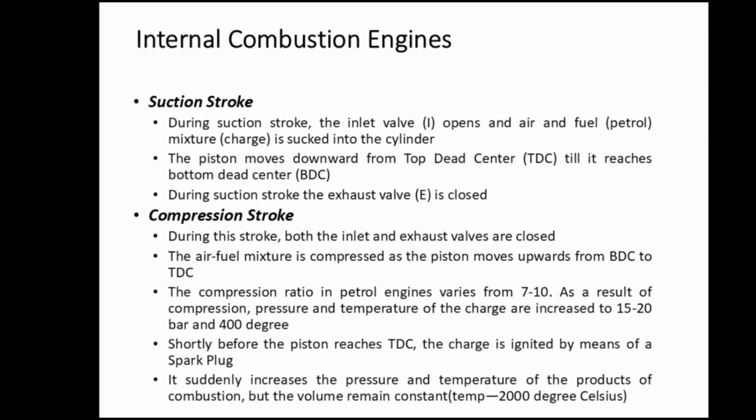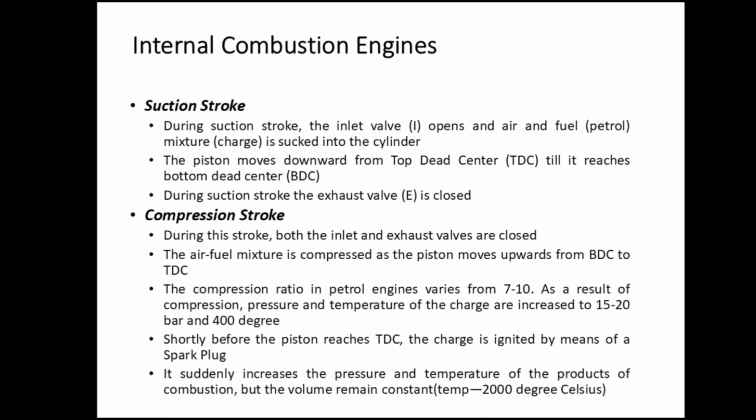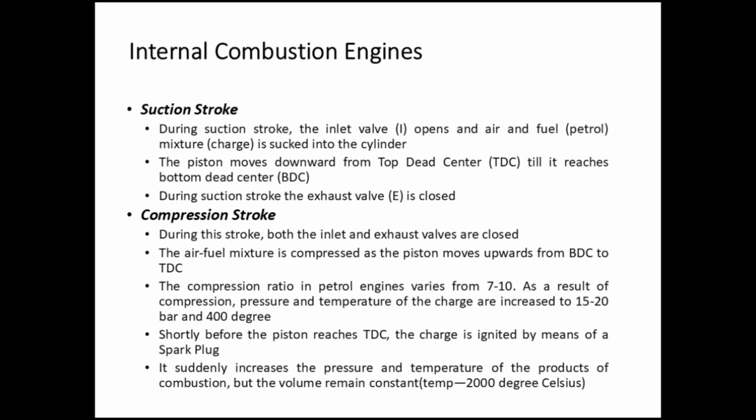Internal combustion engines, suction stroke. During the suction stroke, the inlet valve opens and the air-fuel mixture is sucked into the cylinder. The piston moves downward from top dead center till it reaches bottom dead center. During the suction stroke, the exhaust valve is closed. Compression stroke. During this stroke, both the inlet and exhaust valves are closed. The air-fuel mixture is compressed as the piston moves upwards from BDC to TDC.